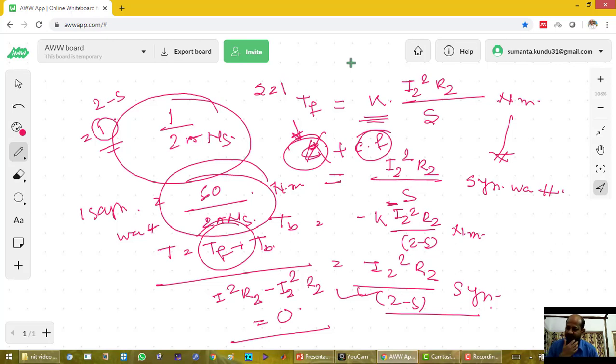So in this fashion the single phase motor can be constructed as a self-starting motor. In my next class we will develop the equivalent circuit of the single phase induction motor with the help of double revolving field theory, and we will also discuss how this initial thrust can be given to the rotor, that is, different methods to start the single phase induction motor.